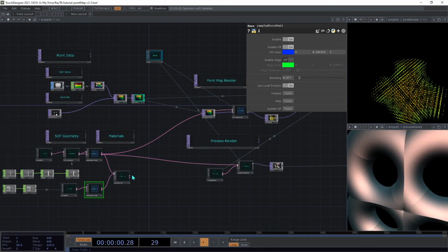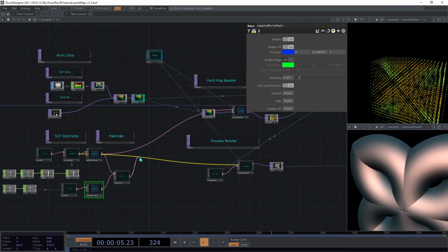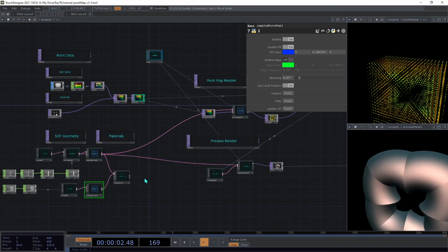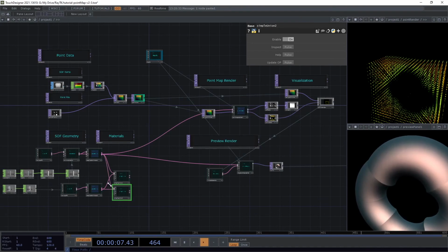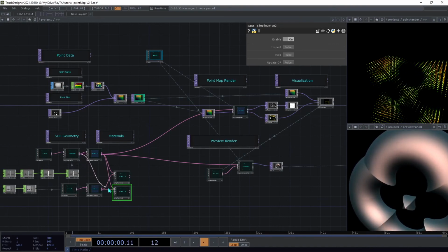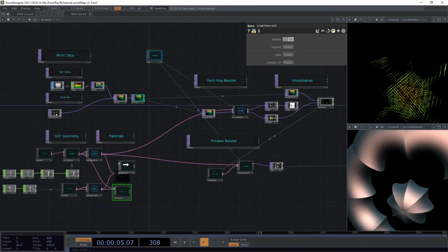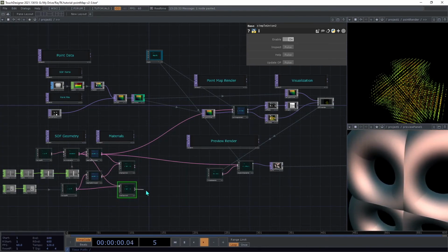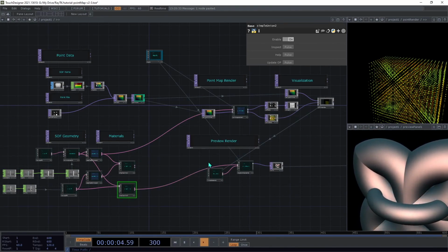Now, if we were to just directly connect this to the Raymarch renderer, you would get that same issue with that type of material not being supported. So instead, we're going to have another simple union, and then this one is going to be connected directly to those source shapes, skipping over those materials. So we move that up there. We've got this other one here. And we can connect that to the Raymarch renderer, so you now see those two different shapes there.